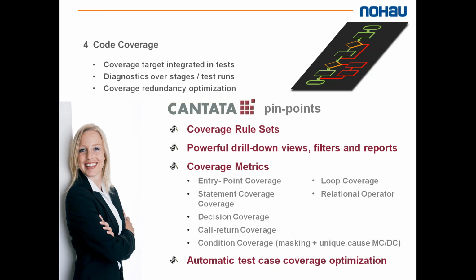That's also a nice feature in Cantata because when you want to have very high coverage, you usually need to generate very many test cases. Of course, depending on how complex your unit is. So, and that's yet another indication that you should keep your units as simple as possible to minimize the number of test cases, because every branch you have in your unit under test requires at least another test case.